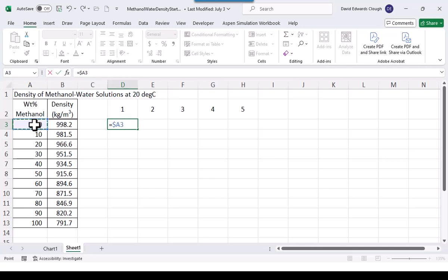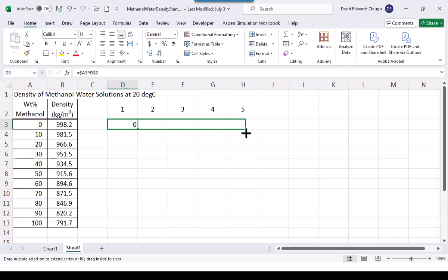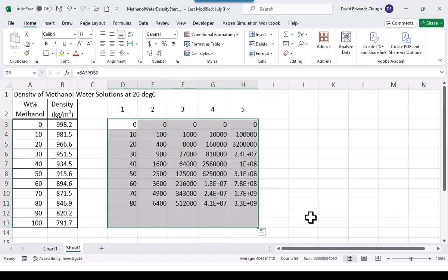That locks the A column, but not the row, to the power up here, which is in this case just one, and I'm going to hit the F4 key twice, which locks row 2, but lets the columns vary. And then I can come over, and these, of course, are going to be somewhat boring, up to the 5th power, and then down here to the 5th power.